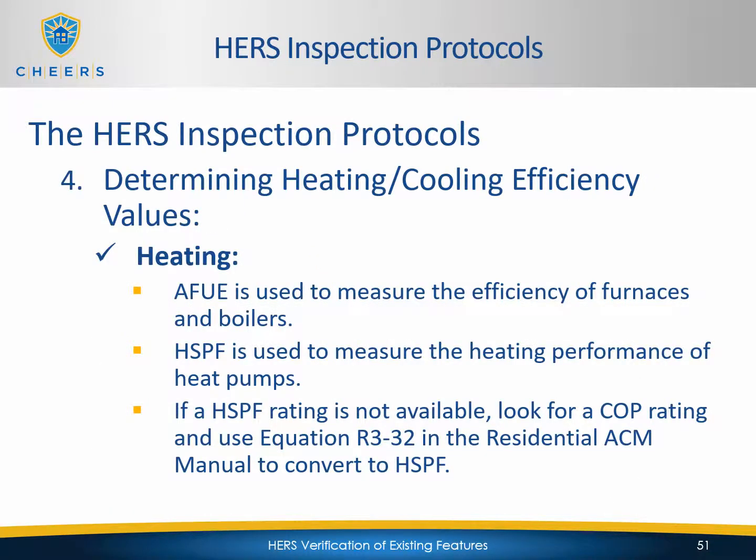AFUE is used to measure the efficiency of furnaces and boilers. HSPF is used to measure the heating performance of heat pumps. If an HSPF rating is not available, look for a COP rating and use equation R3-32 in the Residential ACM Manual to convert it to HSPF.